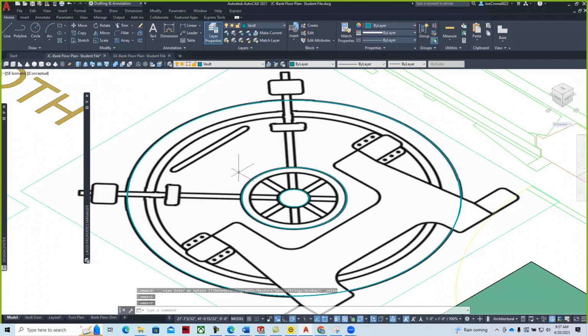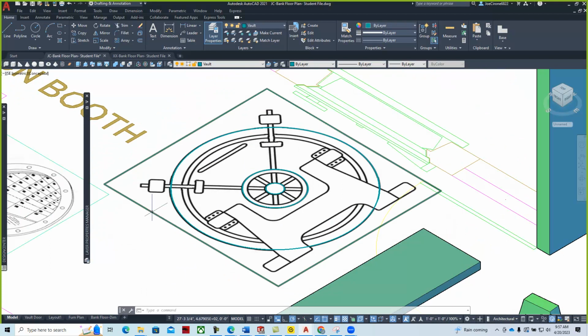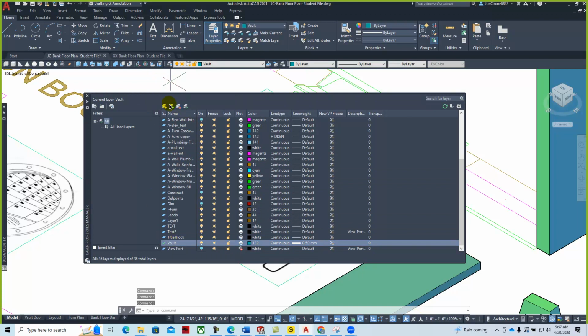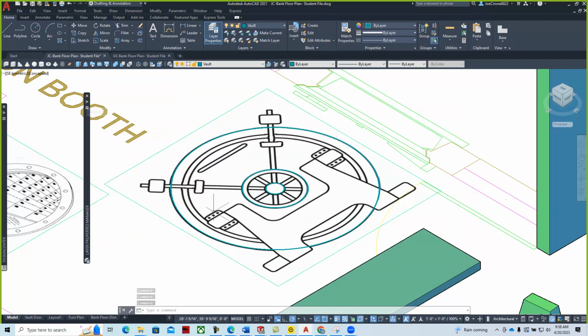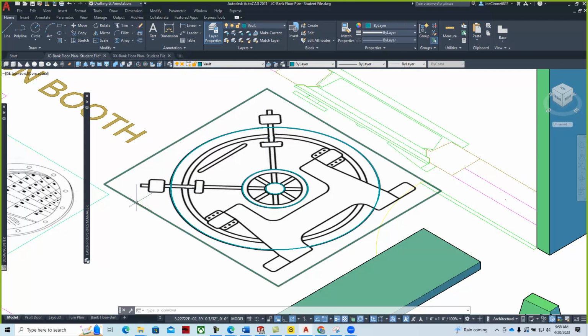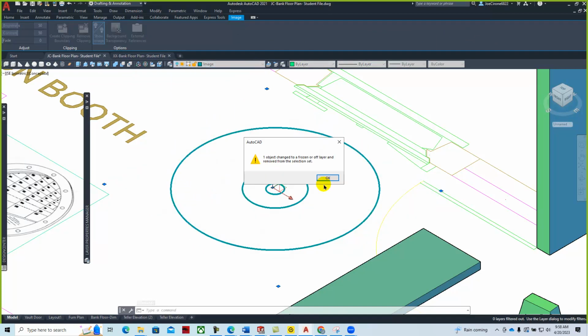Depending on your modeling abilities, we can turn on and off the layer for certain things. So I'll make a layer called image. I'll turn that layer off for right now, and I'll toggle it on and off as we go through so I can see the model for it. It is off already, and I'll put this on that layer. And then I'll say okay.